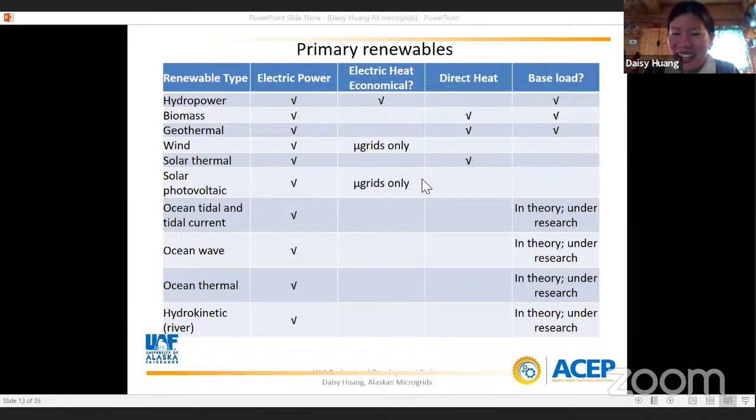I told you that diesel cannot be light loaded, not below 20%. But let's say you're a small community and you put in a wind farm. Well, wind varies a lot. You've put up a Met tower for a year, you've gotten all this data, you know what kind of wind turbines to buy and how much power they'll make, so you put in your wind turbines. But there are days when the wind blows stronger than you need, and your wind approaches the point where it takes over most of the grid and it's stressing out your diesel. So at that point, you actually have to curtail wind.